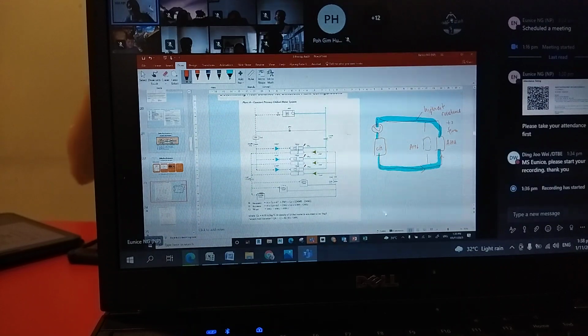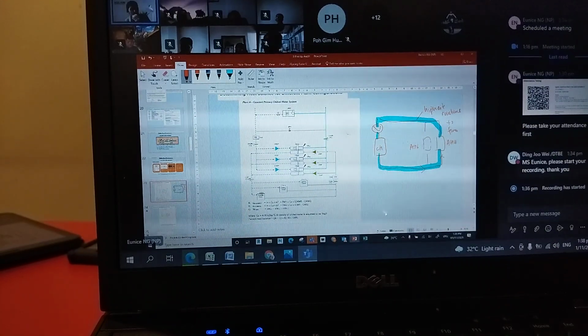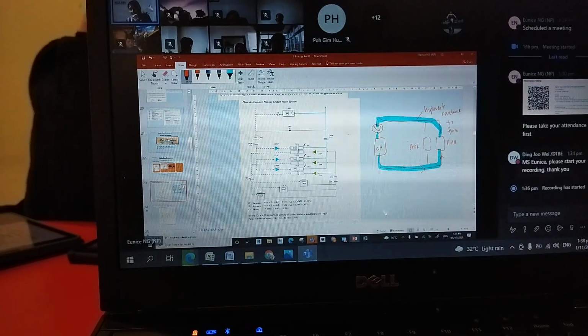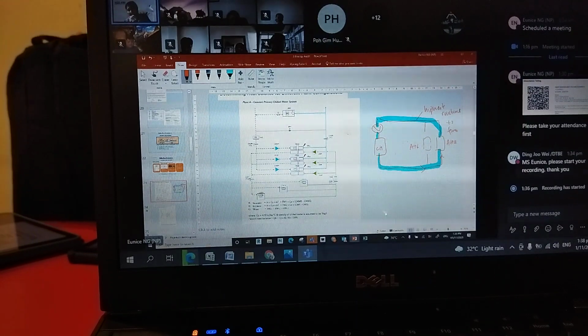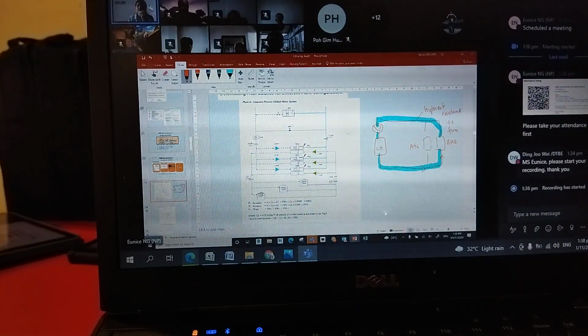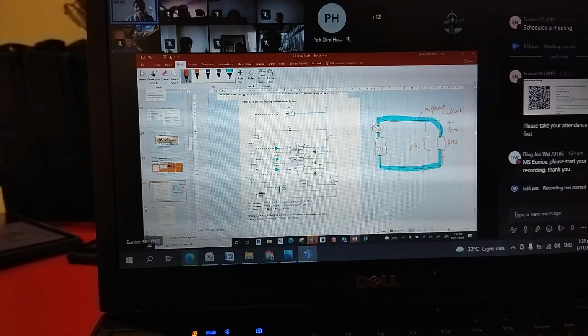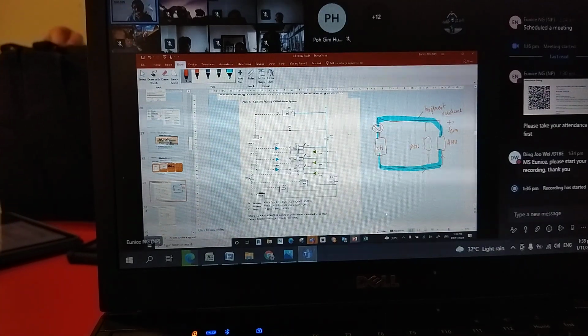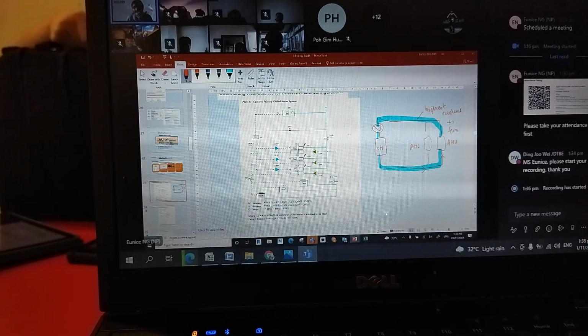So this pump is actually quite a big pump to meet all the loops, to ensure that water can reach the last loop with the most critical path. Because the pipe to that AHU may be very long, it is the furthest away, and there are many restrictions because of the number of bends in the pipe, and so on and so forth. So this pump will be sized quite big, which is not an issue, but it's also constant speed and doesn't take advantage of variable speed drive. So this pump will consume a lot of energy.